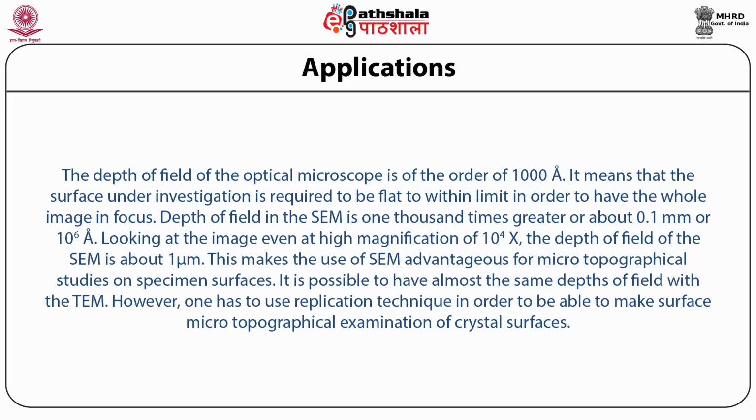Looking at the image, even at a high magnification of 10 raised to power 4 x, the depth of field of the SEM is about 1 micrometer. This makes the use of SEM advantageous for microtopographical studies on specimen surfaces.